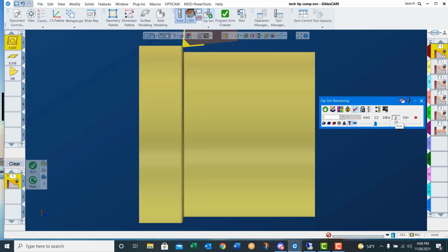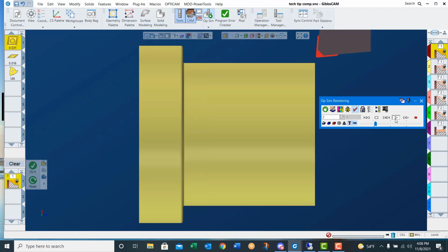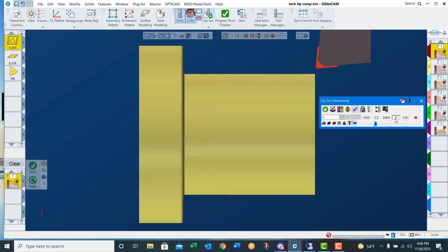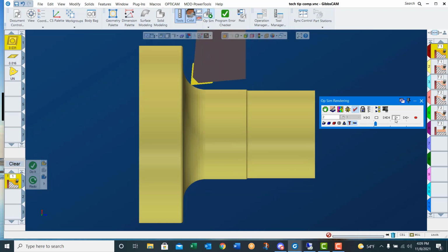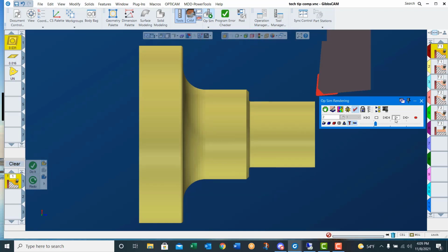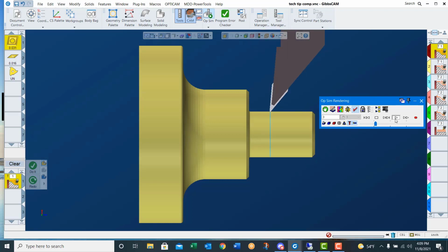In this month's Tech Tip, we will demonstrate how to use and save processes. Saved processes reduce the amount of time needed to program a part and allow you to save custom tools and tool holders along with information such as stick-out length and comments. All speeds, feeds, and depths of cut will also be saved in the process. This makes for a more consistent look to your programs.